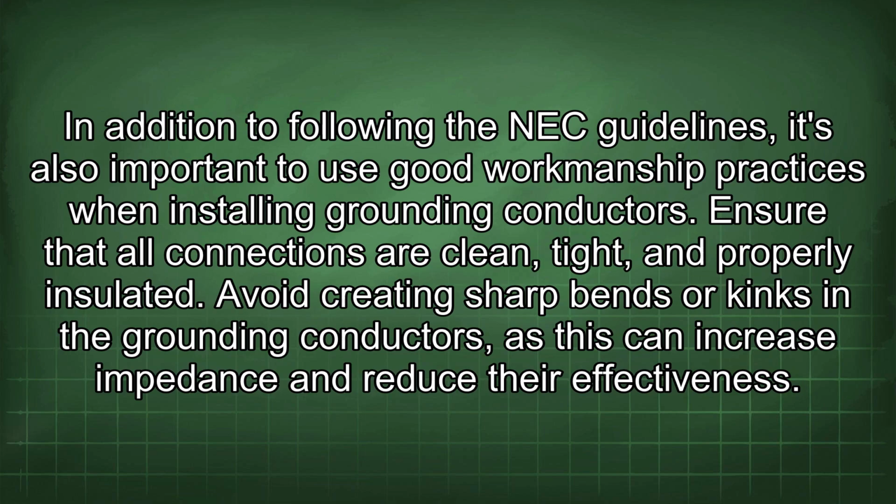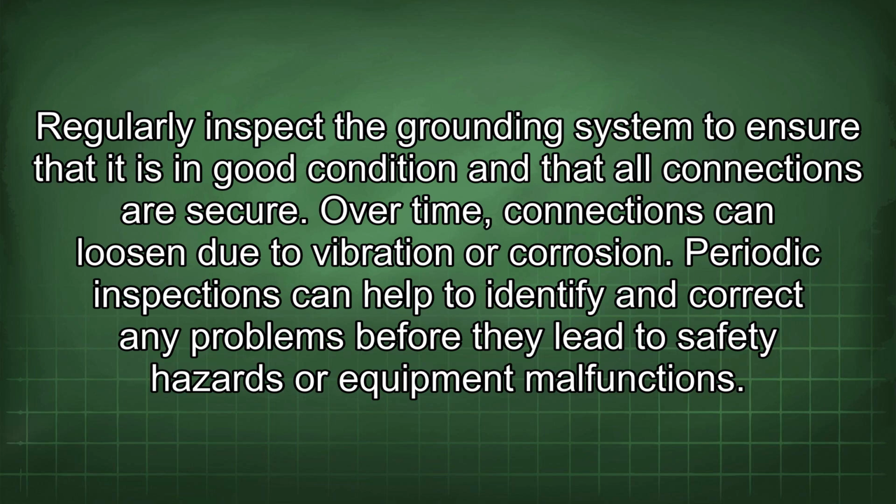In addition to following the NEC guidelines, it's also important to use good workmanship practices when installing grounding conductors. Ensure that all connections are clean, tight, and properly insulated. Avoid creating sharp bends or kinks in the grounding conductors, as this can increase impedance and reduce their effectiveness. Regularly inspect the grounding system to ensure that it is in good condition and that all connections are secure. Over time, connections can loosen due to vibration or corrosion. Periodic inspections can help to identify and correct any problems before they lead to safety hazards or equipment malfunctions.